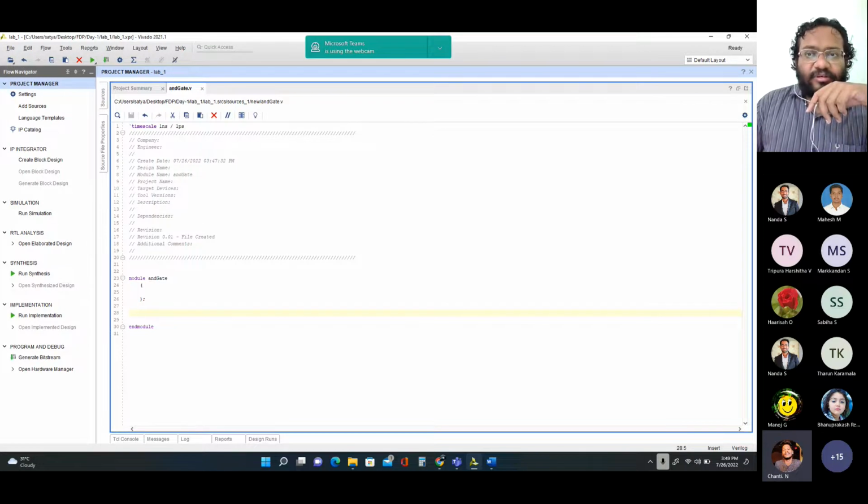So here what you are doing is describing the hardware in terms of a high level language, that is Verilog. From this Verilog language the circuit will be realized. This is the key principle. Between the module and the endmodule you have to describe the circuit functionality using Verilog. The first thing after module is the opening and closing parenthesis, within which you have to declare the port list that I told you.